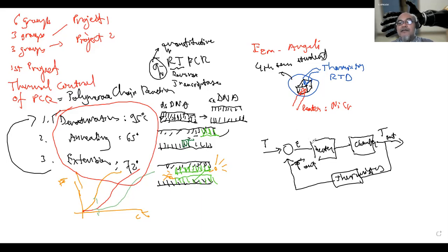Sorry, here there's supposed to be a microprocessor, the microcontroller, the Arduino. The microcontroller will then send the correct signal to adjust the current or voltage to the heater, such that it will heat up or slow down or cool down. You could add an additional actuator, for example, Peltier cooling.